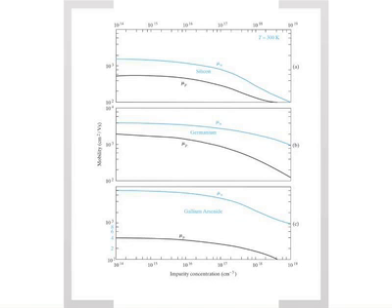Remember, mobility increases, concentration increases, current increases. That's roughly the way to think about it. But if mobility drops, current also drops. So you're trying to increase the concentration, but mobility is dropping. So there's a sweet spot where all of this should work, depending on what your device characteristics should be. And of course, you can calculate that very easily based on the equations from last week. Just drift current.